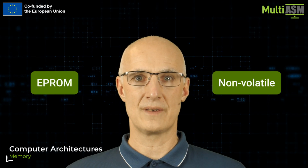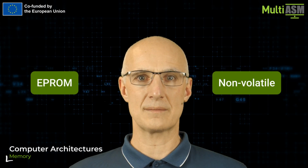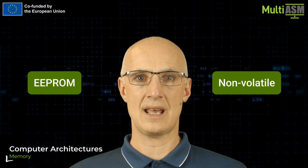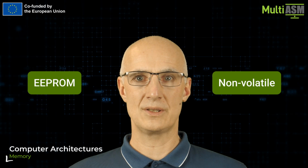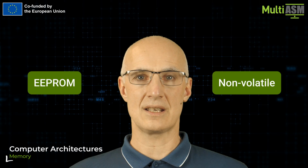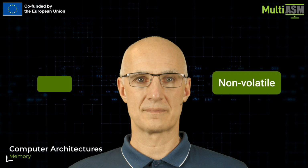This kind of memory was very popular a few years ago, but due to a complicated erasing procedure, it was replaced by electrically erased memories. EEPROM, electrically erasable programmable read-only memory, is a type of non-volatile memory that can be erased and reprogrammed many times with electric signals only. They replaced EPROM memories due to the ease of use and the possibility of reprogramming without removing the chip from the device. The producers ensure that the data retention is for at least 10 years. In EEPROM memory, every byte can be individually reprogrammed.